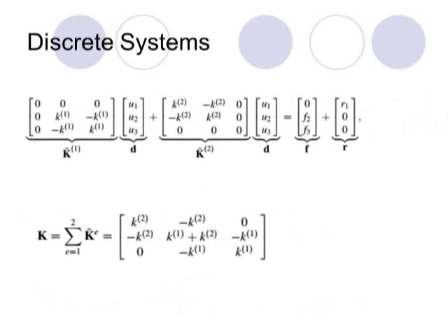Okay, if I substitute these expressions into the force equilibrium, now I have this, because these are the forces, right? These two expressions give me the internal forces, and I have external forces which I know, and I have reaction forces. As a result, the global stiffness of a system is the sum of the elemental stiffness matrices.